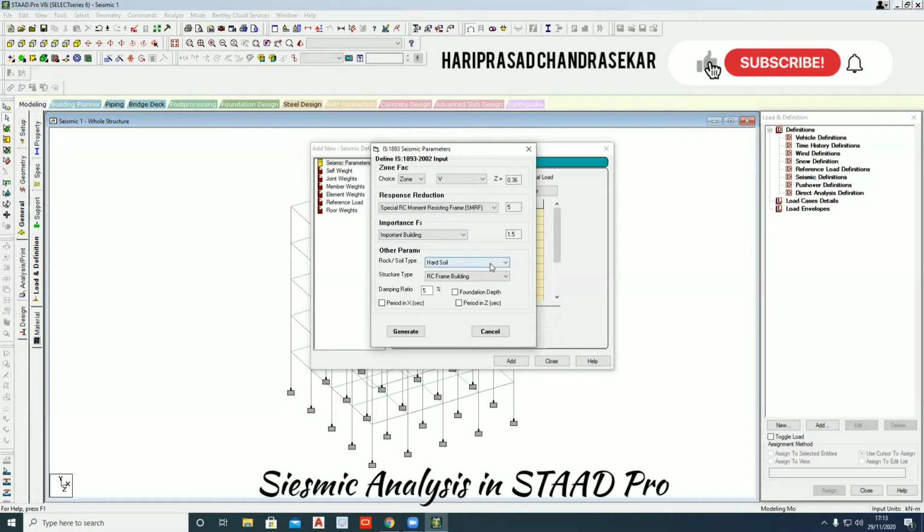Okay. And then rock or soil type: hard soil, medium soil, soft soil. It depends on the soil condition that you have. Anyway, I'm going to use medium soil. And then structure type, RC frame structure. If it is a steel frame structure, you can select steel frame structure. Anything apart from this, you can choose all other buildings. Here we applied concrete only, so that's why I'm choosing reinforced concrete, RC structure.